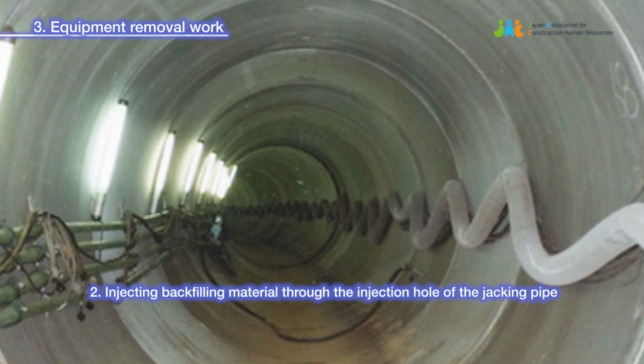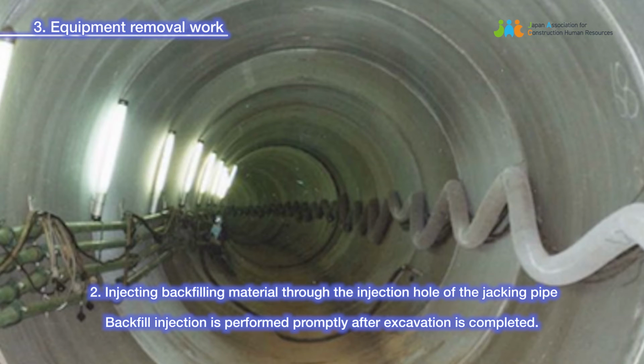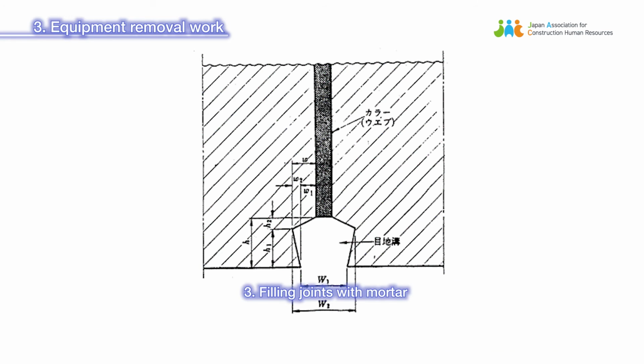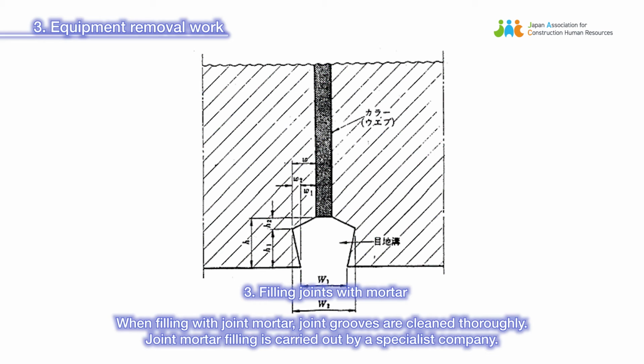2. Injecting backfilling material through the injection hole of the jacking pipe. Backfill injection is performed promptly after excavation is completed. The injection fitting is connected to the appropriate location. During injection, monitor outflow from the joints and start and arrival shafts. 3. Filling joints with mortar. When filling with joint mortar, joint grooves are cleaned thoroughly. Joint mortar filling is carried out by a specialist company.